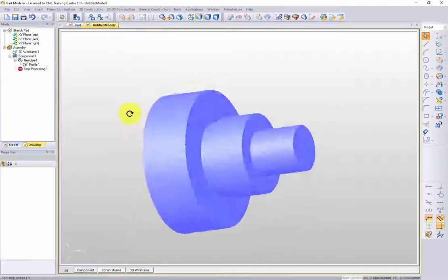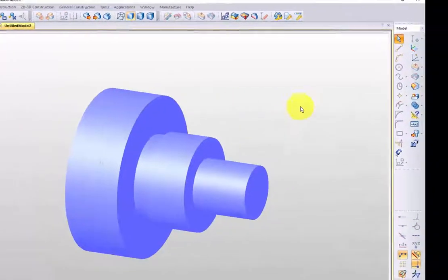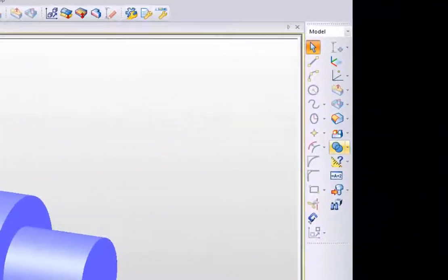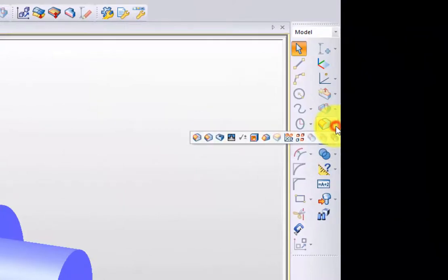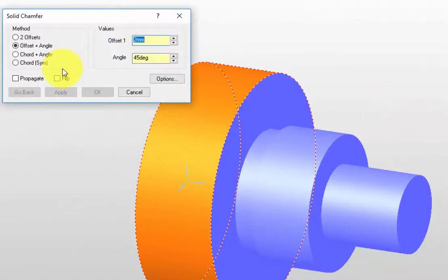But something that's worth noting is that when you start adding construction planes, if you want them to edges and you've got chamfers on, sometimes those construction planes just don't work out right, and you end up extracting geometry and things like that. So I think it's always a good idea to leave it right till the end to put all these chamfers and rads and things on.